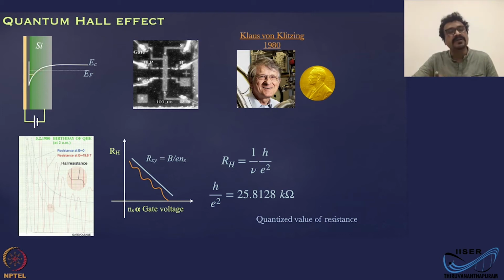That is actually a two-dimensional system where, in the z direction, which is perpendicular to the plane of this substrate, you have only one momentum state, or there's only one k state. So then you can assume that that's a two-dimensional system. Okay, but the charge carriers, as we discussed in the gallium arsenide, aluminum gallium arsenide two-dimensional system, are free to move in the plane, but they cannot move out of it. There is no momentum state available for the charge carriers to scatter in the z direction.